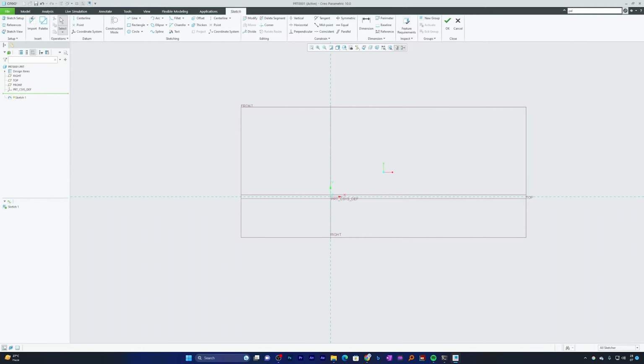And now let's talk about applying geometry constraints. Geometry constraints help us define the relationship between sketch entities, such as parallel, perpendicular, horizontal, and many others, as you can see listed here. Now let me quickly show you some examples. You may see that some automatic constraints are recommended by the software even when you are just plotting the sketch. These kinds of constraints are also known as on-the-fly constraints.